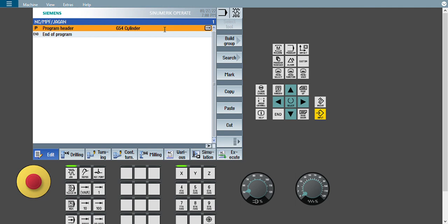Today we will learn how to do the grooving cycle in the ShopTurn programming method. In this method, we have different types of grooves, so that on the basis of different applications we can use various types of groove cycles. Usually if we are going for grooving, we always think about what the tool is, what the material is, and what the cutting parameters are. We need to understand all of these before going to the grooving cycle.